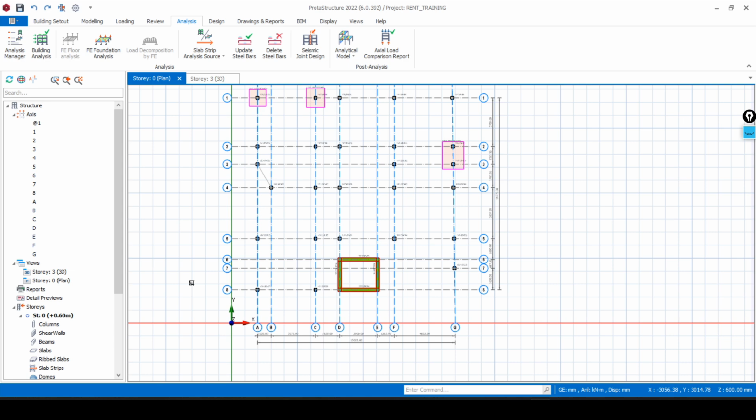Okay, so when this building is going to be imposed upon, it depends on the activity. If this building is going to be imposed by cars and others, maybe it's a building that is going to be used for parking cars or shopping areas, you are going to find out that the loadings on this building are going to make it very heavy. That is what is going to cause the pad foundation size to be too large. So what that simply means is that you are going to change the type of foundation.